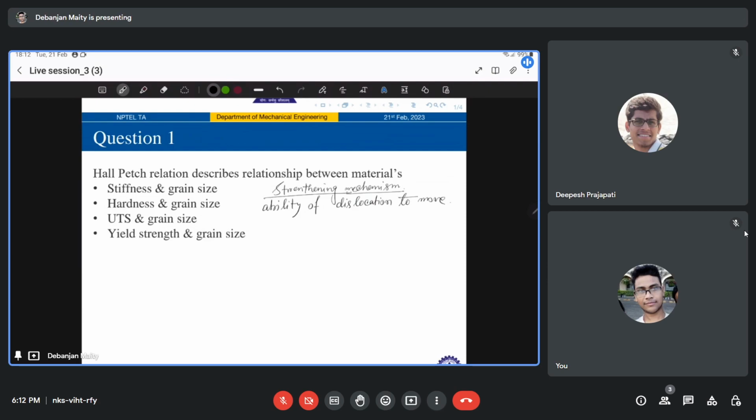Now hardness and strength are related to how easily a metal plastically deforms. So by reducing this dislocation movement, mechanical strength can be improved. And to the contrary, if dislocation movement is very easy, or unhindered, the metal will be soft and easy to deform, right?